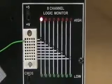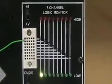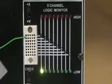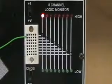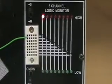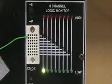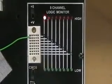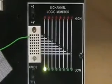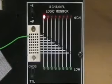The 8-channel logic monitor, located at the upper right of the board, is an array of 8 channels used for testing the output of your digital circuit. The red LEDs signify a logic level 1, which can be set to either positive 5 volts or positive V being set at the top of the board. The green LEDs signify a logic level 0, which is typically ground. The monitor also allows you to define what type of integrated circuit you are testing, TTL or CMOS.